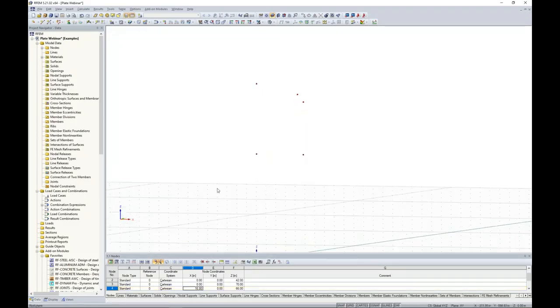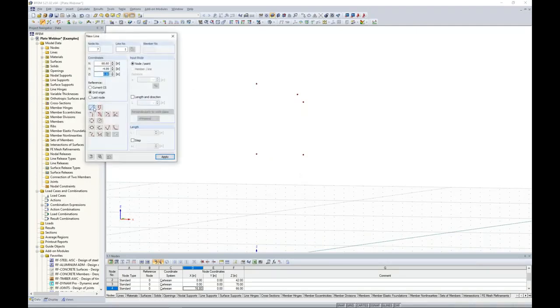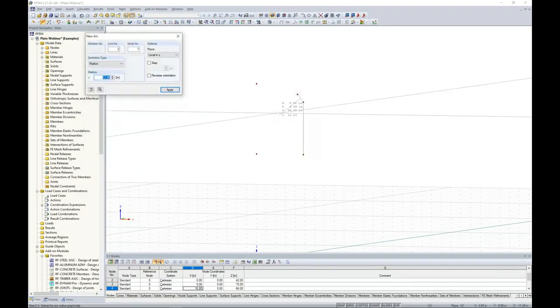with line elements. And for this, I will go to the option up here in my tools to draw a new line. The first line segment will just be a simple straight line where I'm going to connect this bottom node to this top node. But my next line element, I would actually like it to be an arc. So we have the ability here to define an arc, and I can select from one node to the next.